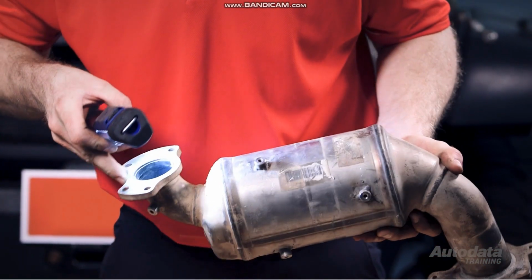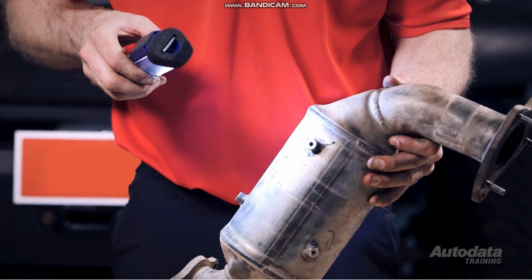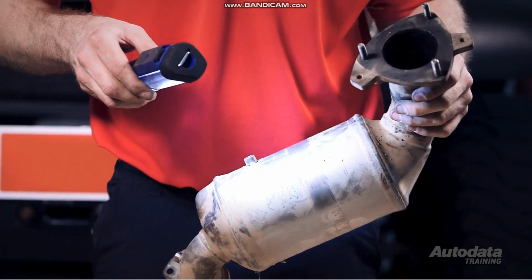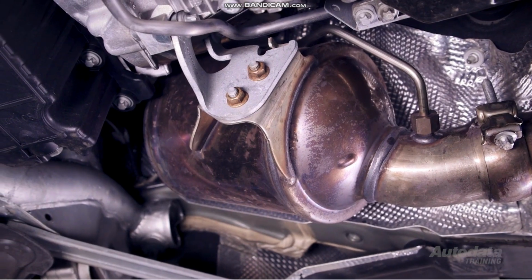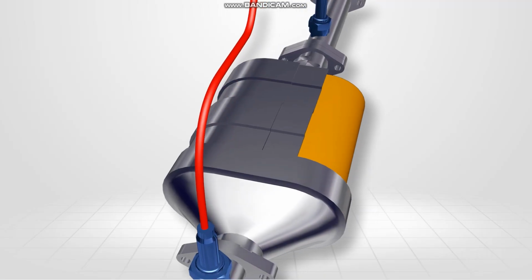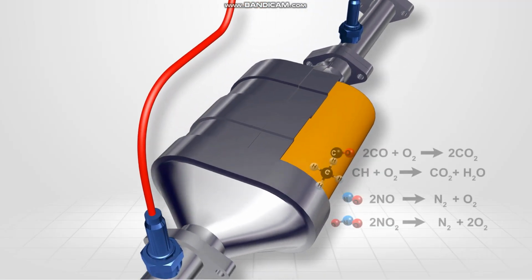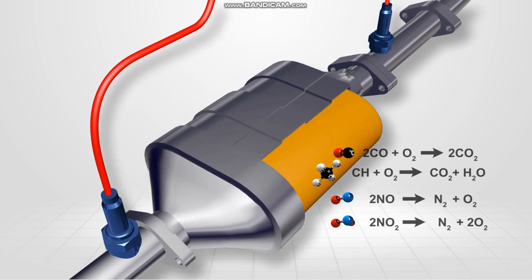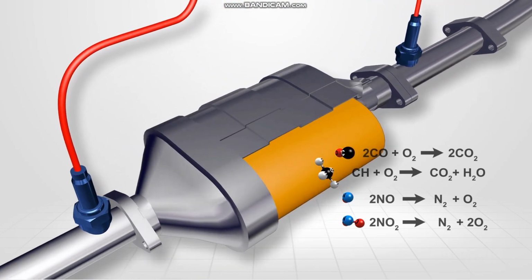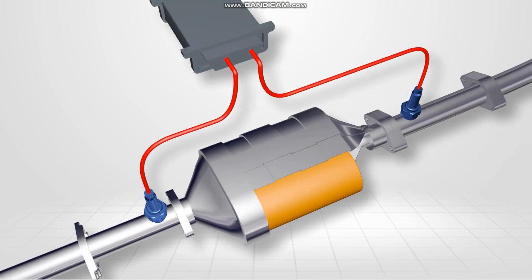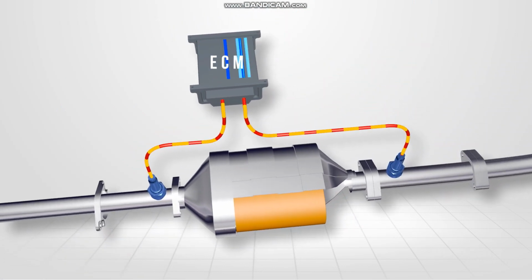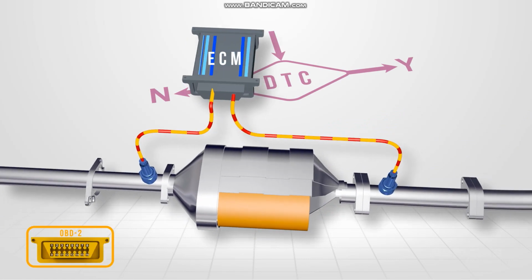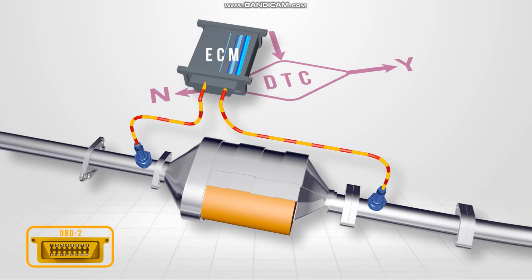With any modern vehicle, the first key component to protect in the engine management system as part of OBD2 is the catalytic converter. The converter is responsible for the conversion and reduction of harmful pollutant gases before release into the atmosphere. The catalytic converter is closely monitored by the engine management system in all modes of engine operation as part of the OBD2 standards and their equivalents.